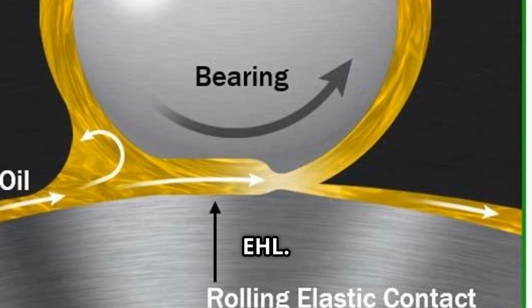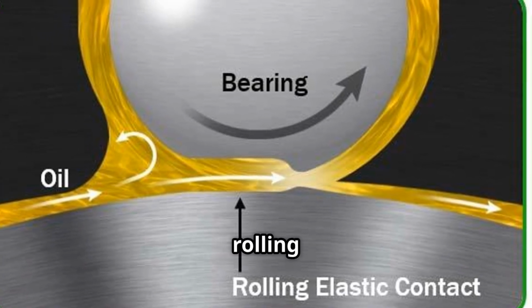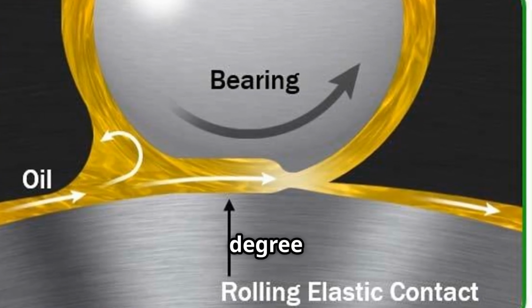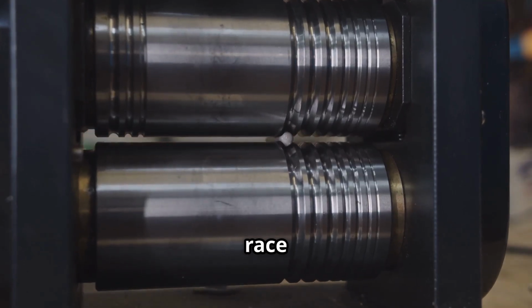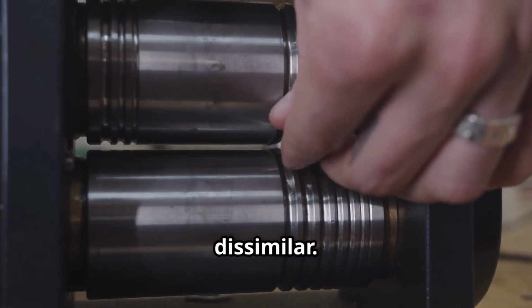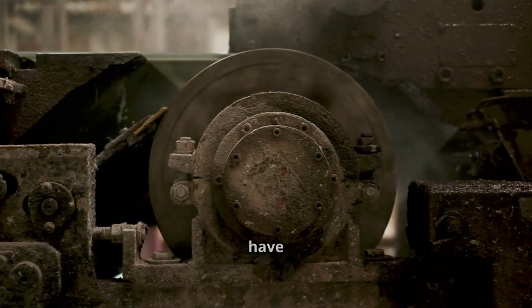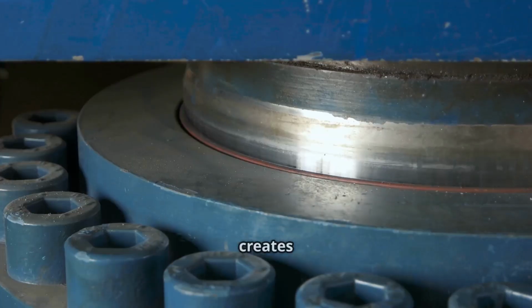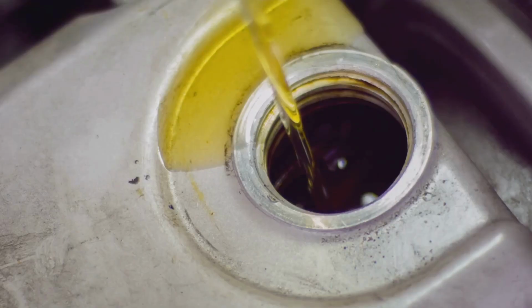Elastohydrodynamic lubrication, or EHL. Elastohydrodynamic lubrication conditions occur when a rolling motion exists between the moving elements, and the contact zone has a low degree of conformity. For example, note that the curve of the roller and the race in a rolling element bearing are very dissimilar. In fact, the roller and inner race are curved in opposite directions and thus have a small contact area, almost a single point of contact. This creates high contact pressures, hundreds of thousands of psi.